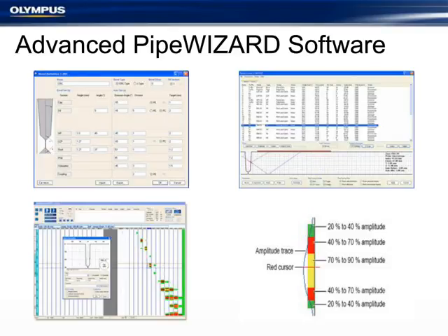And then when we get data back, instead of looking at a color image of all the beams, we'll look at individual strip charts, and the color and the size of the box inside of it will very quickly tell me the positioning on the side of the fusion line as well as its amplitude. So we can make very quick, detailed calls and then go in and do more precise measurement as needed.